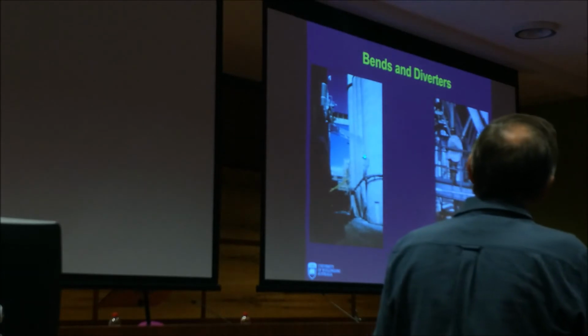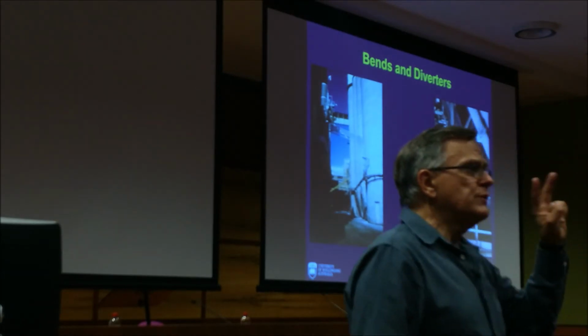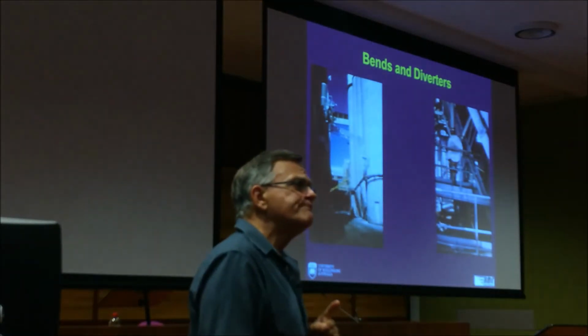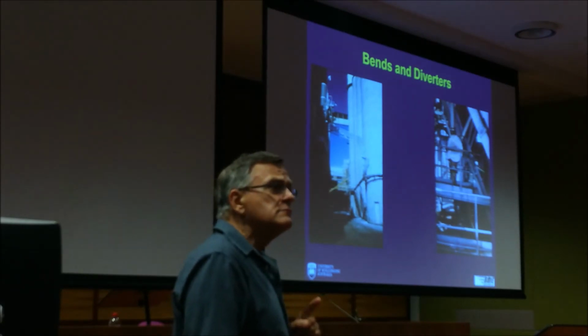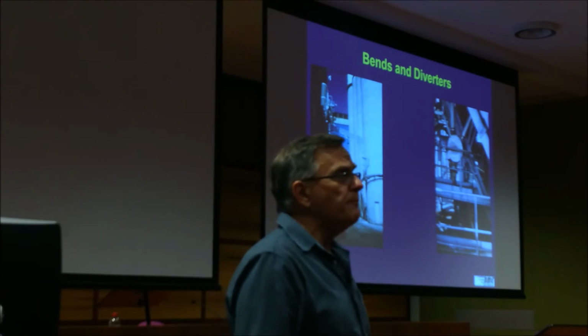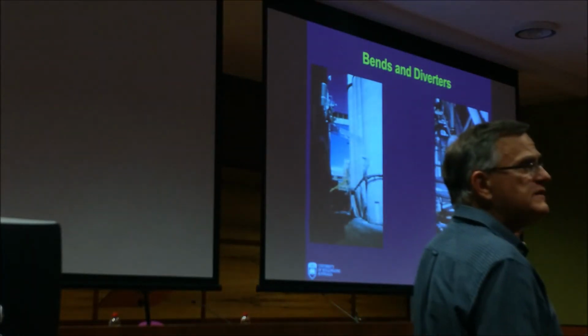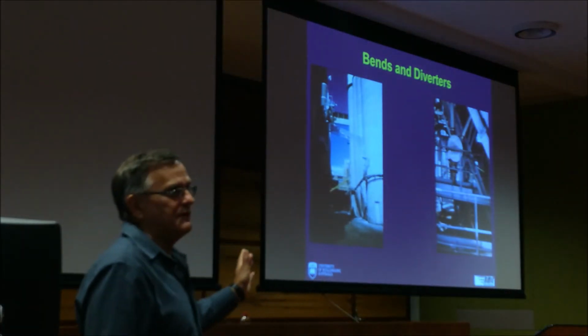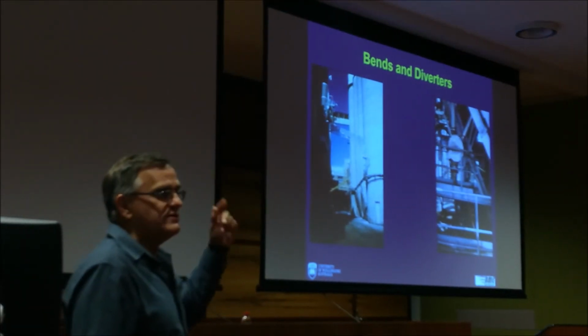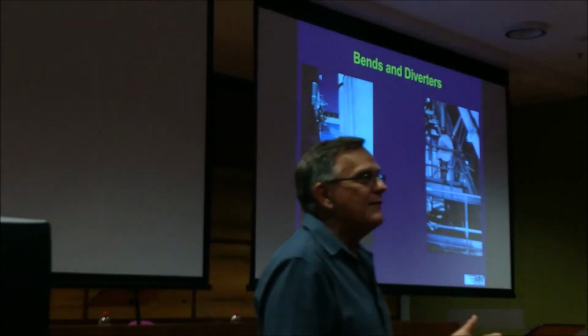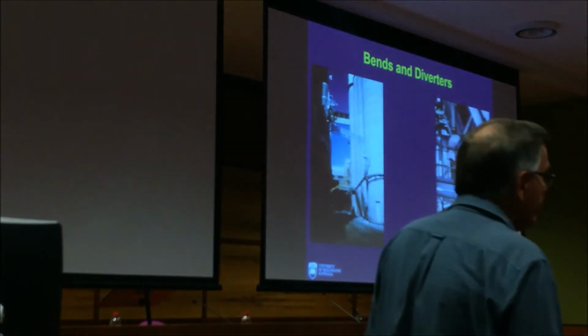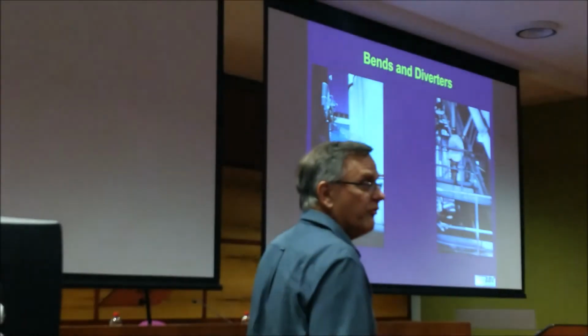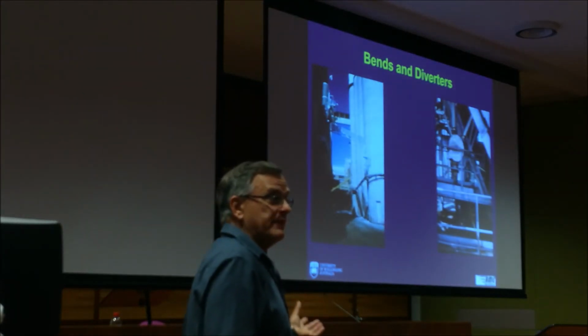Bends give us flexibility, but there are two issues with bends. One is wear: every bend will wear, so there are maintenance issues, and every bend produces pressure drop. So the more bends give you flexibility, but you also need more energy or more pressure loss to overcome. It equates to kilowatts and power, and dollars, running costs, compressor side, blower side. All these things add up at the end of the day.